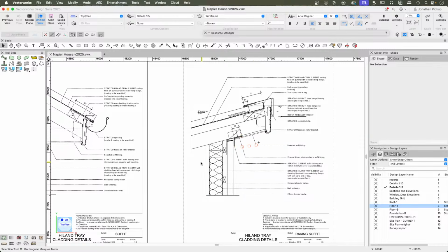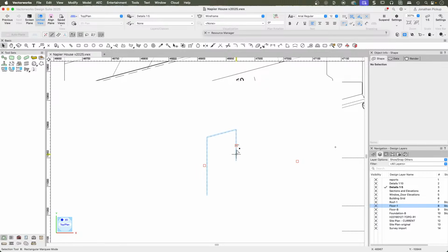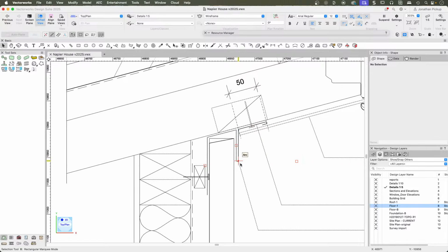Now, if the pressure inside is lower, it can suck water in. So for example, here we've got our flashing. The water wants to come up here, but it can't get up here beyond this point, and it dribbles out. But if this was a touching point here, and the water could suck up there, and the surface tension could drag that across, then it would fall down here. But of course, it can't get across this gap, and the water would drain out of the cavity. So again, the cavity is really useful for the drainage.